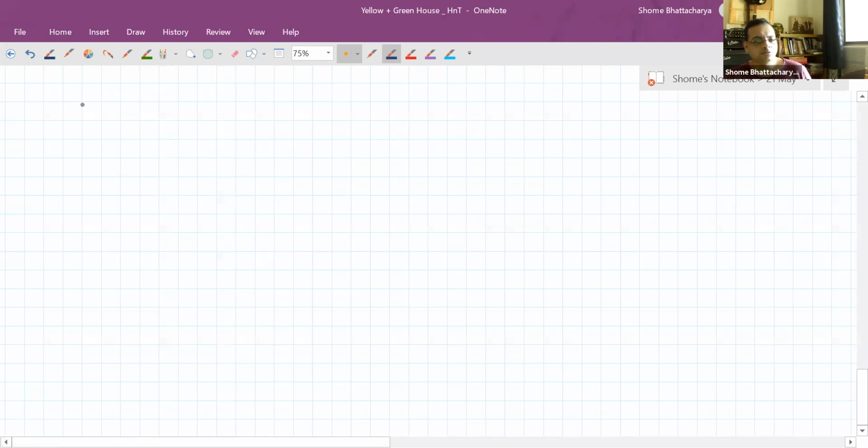Okay, so now let's move on to the last part of this applications of first law chapter, which is cyclic processes. So cyclic processes is nothing new in terms of formulae, but it's just that the process consists of individually more number of processes such that the gas is undergoing a complete loop or a complete cycle in the PV curve. Okay? So any cyclic process is actually a combination of processes such that the resultant change brings the gas back to its initial state.